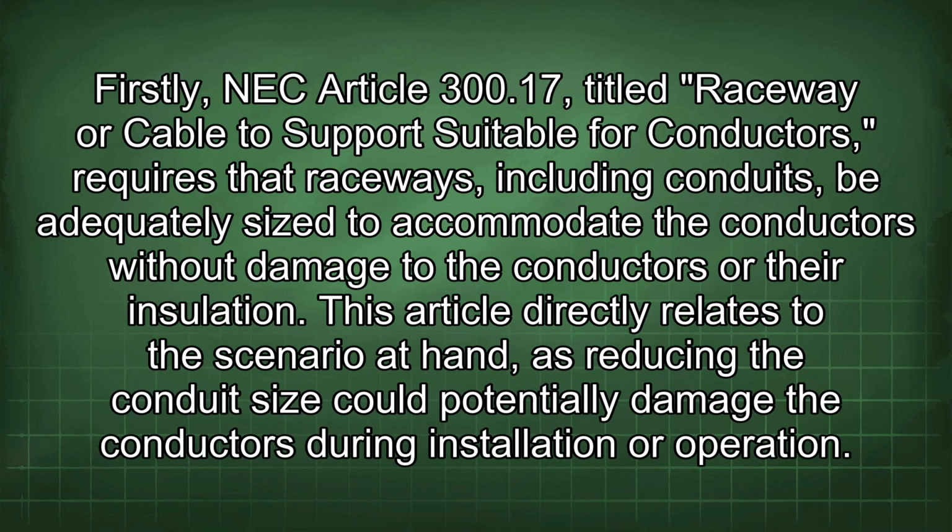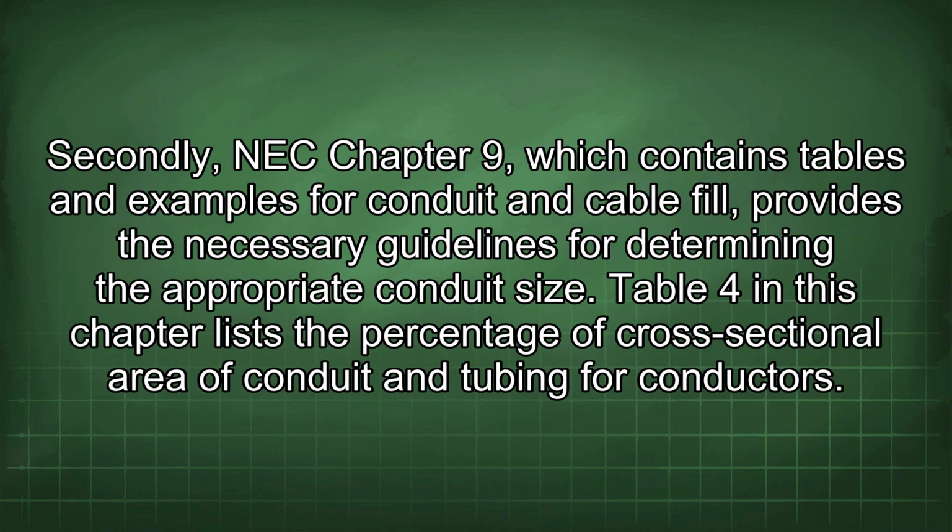Firstly, NEC Article 300.17, titled Raceway or Cable to Support Suitable for Conductors, requires that raceways, including conduits, be adequately sized to accommodate the conductors without damage to the conductors or their insulation. This article directly relates to the scenario at hand, as reducing the conduit size could potentially damage the conductors during installation or operation. Secondly, NEC Chapter 9, which contains tables and examples for conduit and cable fill, provides the necessary guidelines for determining the appropriate conduit size.